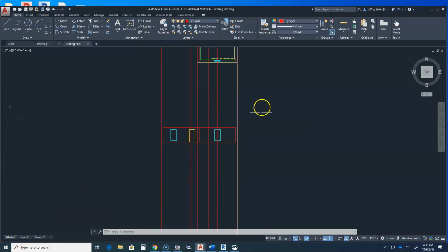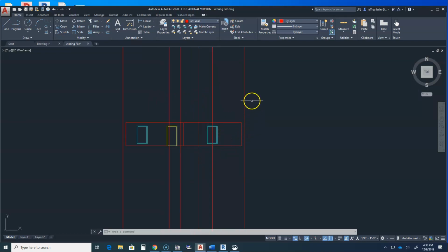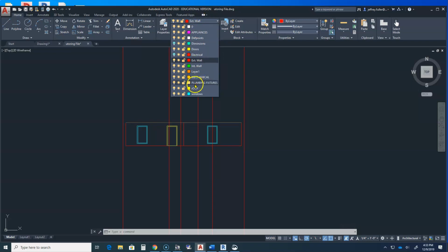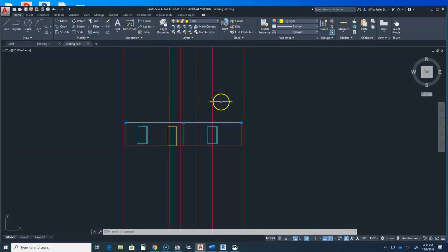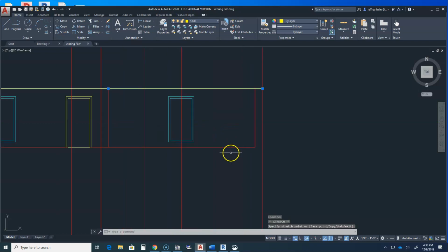After establishing all the construction lines for the south elevation view, go to the elevation view itself and click on the line that represents the top of the wall and activate it. In the Layers drop-down, select the roof layer to reassign the line to that layer. Find the endpoint grips of the line that you just reassigned and extend each side to the furthest left and furthest right vertical construction lines.